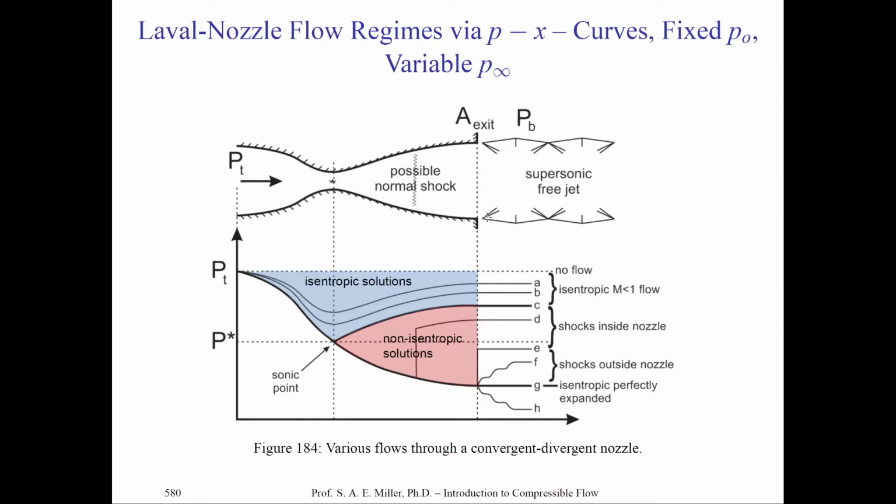Now, if I raise the nozzle pressure ratio, say 1.893 plus epsilon, then of course I will have a supersonic flow coming outside the nozzle, and it would become supersonic at the throat in the nozzle, and it'll become supersonic where my cursor is, and then a normal shock will happen, and then the flow will come back down and exhaust supersonically. So remember, when the normal shock's in the nozzle, of course, we have subsonic flow, according to our normal shock equations and relations for standing normal shocks. If we increase the NPR a little bit more, the shock wave position will move down this curve where my cursor is, according to the on-design condition.